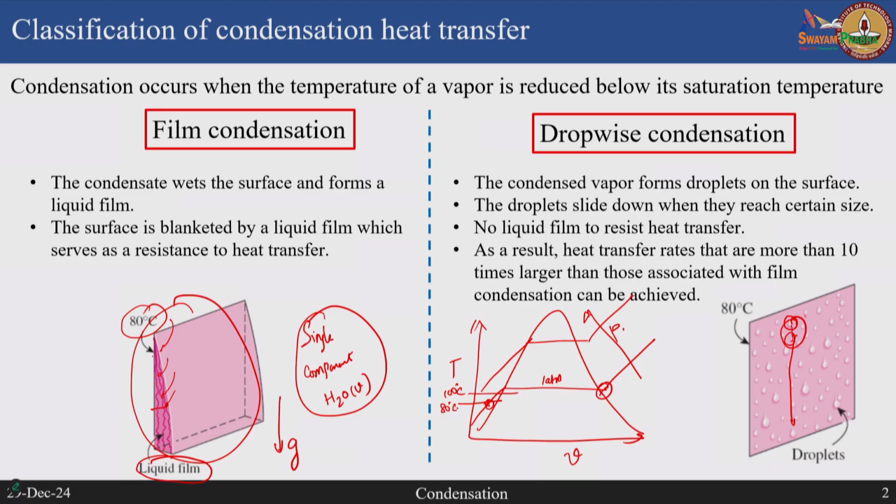Okay, because dropwise condensation requires the wettability of the surface to be changed, it does not happen by itself. Or if you take a surface which by default gives a very high contact angle with water, then that will automatically create dropwise condensation.